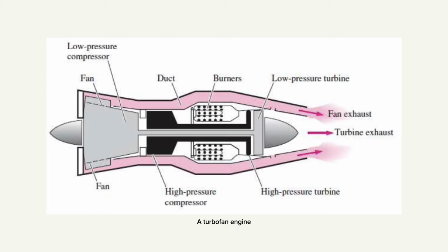air-fuel mixture is then combusted at constant pressure, which further increases its temperature. This air is then allowed to expand in a turbine. This turbine is also responsible for powering the compressor and the electronic components inside the plane. After expansion in the turbine, this air is further allowed to expand in a nozzle, which also increases the exit velocity of the air. This high speed exit jet of air is what is responsible for the generation of thrust.